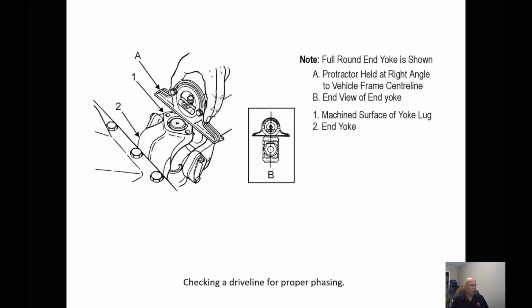So using the inclinometer, one of the things we want to make sure is we take all our angles from the same side. I always do mine from the driver's side: transmission, driveline, differential.